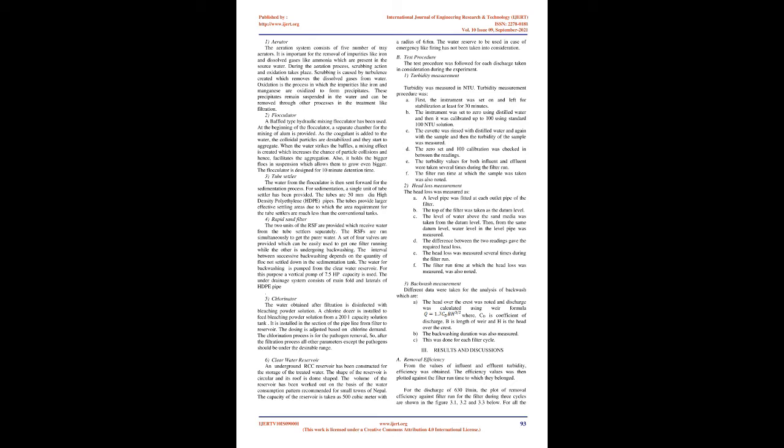RSF are found to perform well when it comes to turbidity removal. A well-operated RSF reduces turbidity to less than 1 NTU and often less than 0.1 NTU too. The RSF are also found to be highly effective in color removal. It brings the color down below 3 on the cobalt scale. However, RSFs are less effective in bacterial removal. Most literatures suggest that they remove about 80 to 90% of the initial bacterial load.